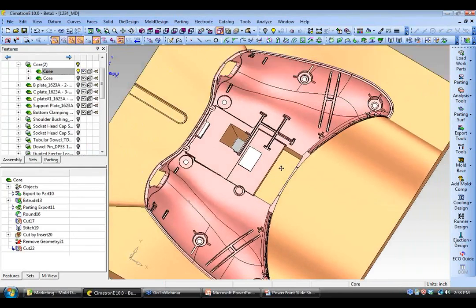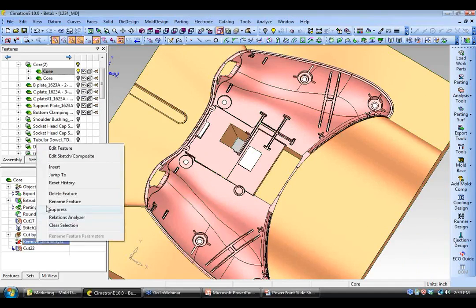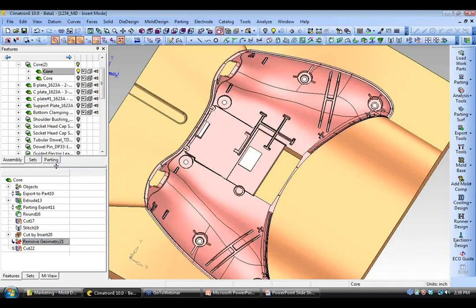And I really have to be careful here not to get too much of a good thing, because I need some of that geometry in order to create the face on the lifter. What I'll do then is step backwards one feature in the history tree of the part. See, I can manipulate the timing of the cut by using the tree. So that lets me do operations in any order that works the easiest for me.